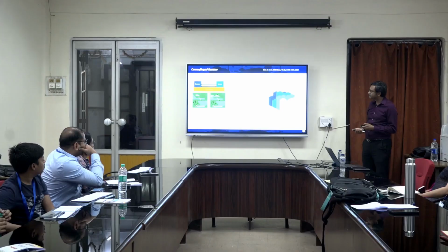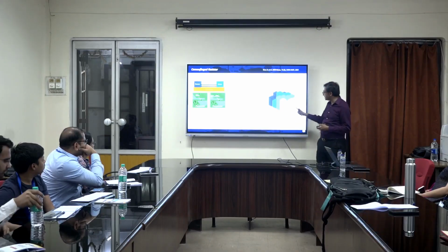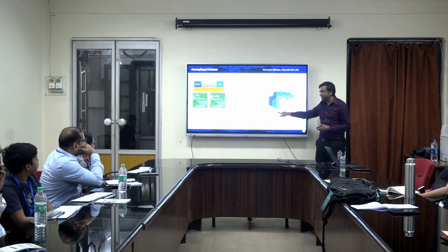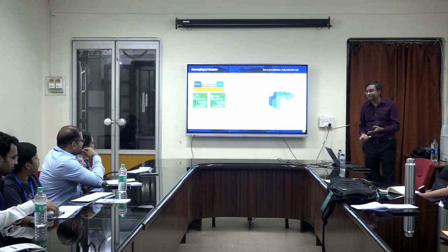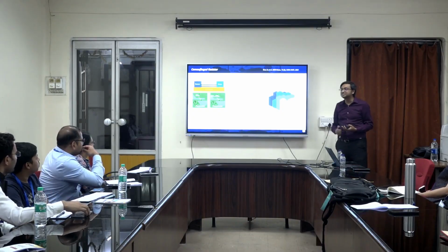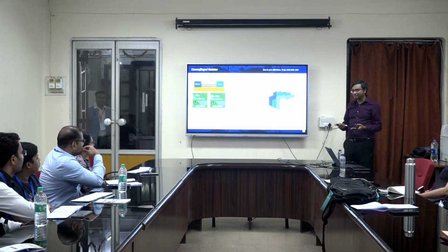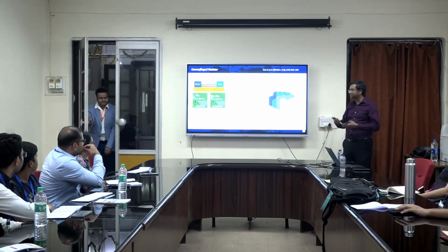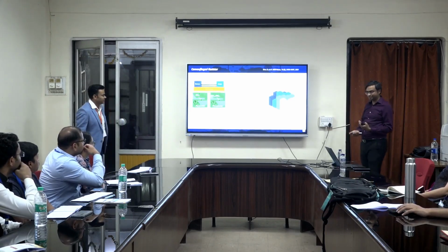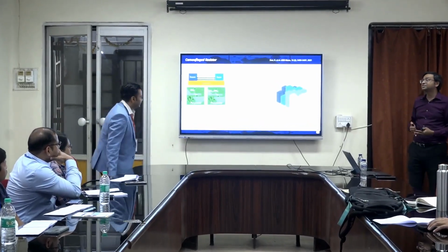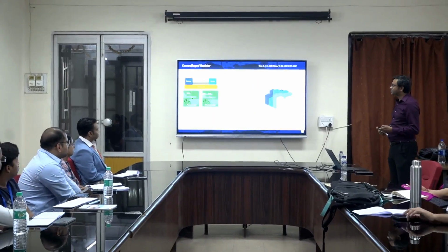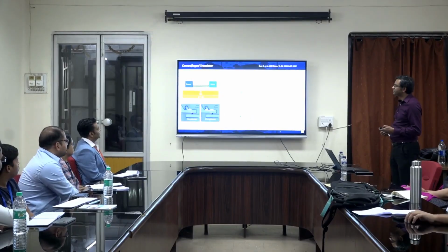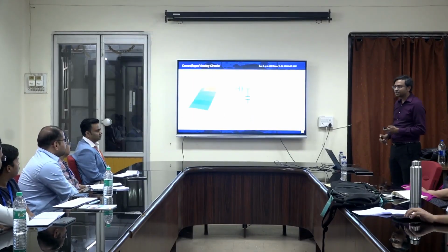just a simple resistor, right? We are talking about a simple resistor. Depending upon the plasma treatment time and the initial thickness of the flake, the resistance could be anywhere. So even if you do a Raman, you might be able to say, okay, I know that it has been plasma treated, but how do I know what is the exact resistance value? And as I told you, that R2R ladder, if the resistance values are R versus 2R, then the function is completely different. So even if you do that, it is even more foolproof. It's difficult. This is where I was talking about this number of trials that is required, right? Remember this plot that I showed? Yeah, this one.